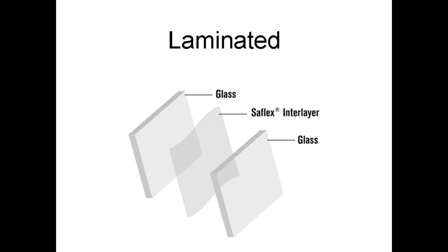So the other thing that we do with glass is to laminate it. It's a process that I've mentioned a number of times through this series, where you're layering it up. This will stiffen and strengthen it, even if you already have toughened glass. The process of laminating will strengthen it further, and you're beginning now to get to a point where you can really take serious loads with the glass. The process of laminating means bonding pre-made glass sections together with an interlayer.